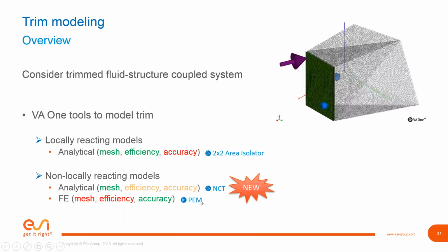And until this last year or two, we've had a much more detailed representation with poroelastic materials that's been more appropriate on the FE or deterministic low frequency side, or for some of the deterministic parts of a hybrid model. We know it's very accurate. It's fully accurate, fully detailed, all the interaction, but takes some time to mesh and set up, some modeling time, both to set up and to run. In fact, running it can take more time than the actual underlying structure of the vehicle. So we've balanced and mixed in a couple new ways to model trim.